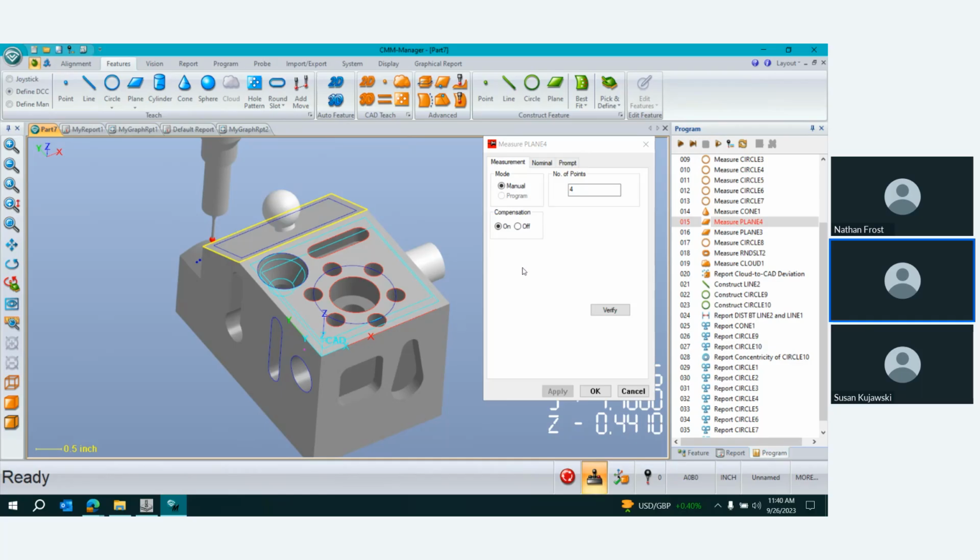Really, there's this capability inside? It's quite surprising, and in a positive way. I didn't know that's possible with the arm. Yeah. With an arm, on a circle for instance, you could simply drag the probe around the circumference of the circle, and instead of having 4 or 5 points, you could have maybe 50 or 60 points immediately. All of those settings would be available here in this dialog for configuring one mode versus another. Otherwise, what you see here would be pretty similar.